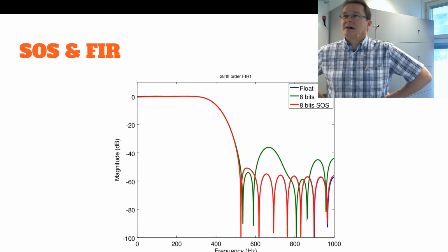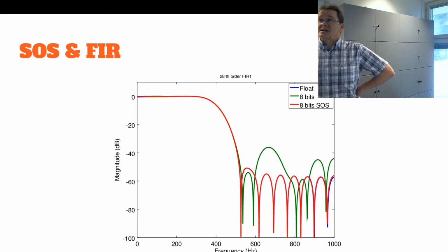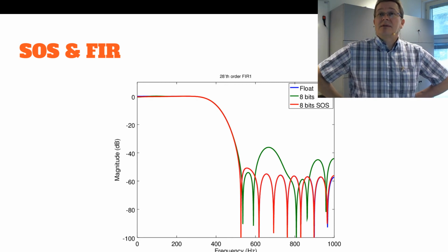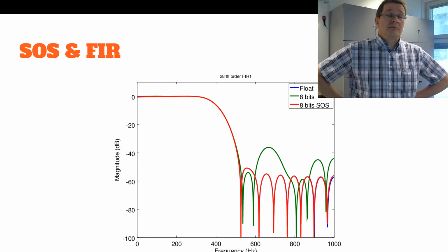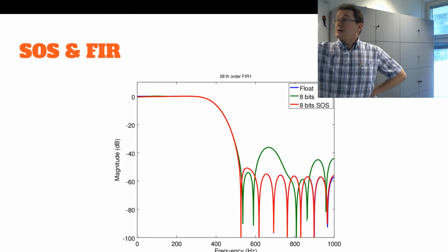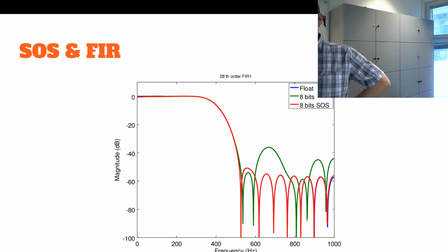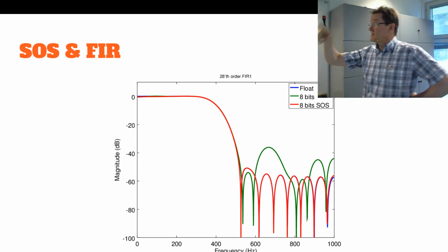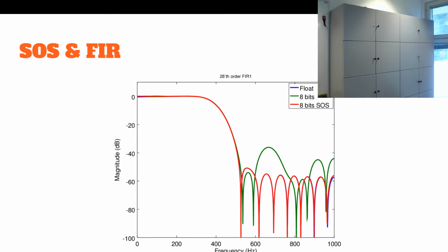Okay, so this is an FIR system showing 8 bits precision of floating point, and then that green one is an 8-bit precision direct form, meaning it has a lot of rounding errors because these are rounded more or less to 0, so the relative error on these is much higher than on the higher values. And if you are using 8-bit second order systems, you are getting the same performance as the floating point. So does it pay to make this division? Yes, it does.